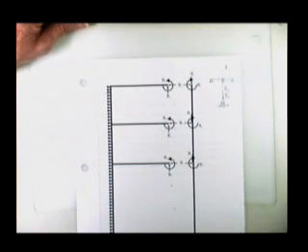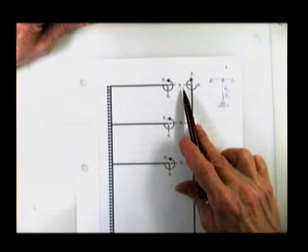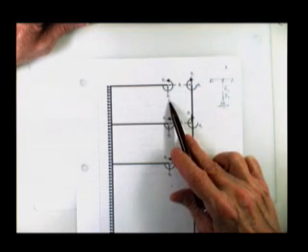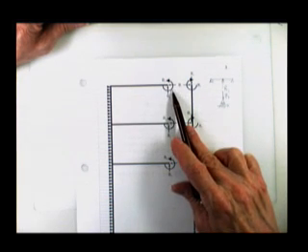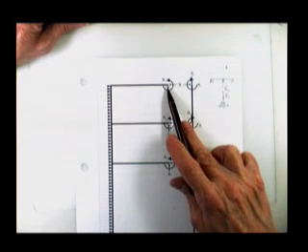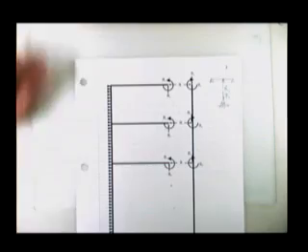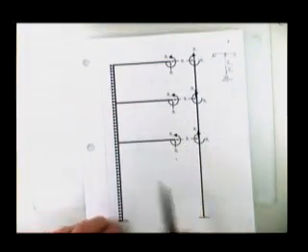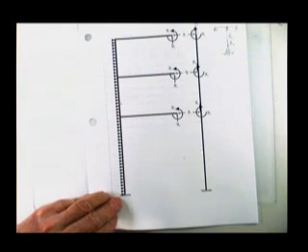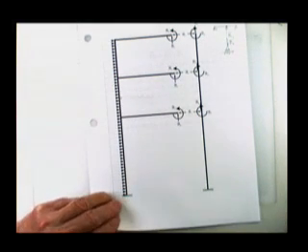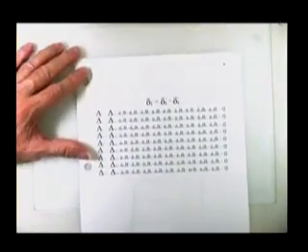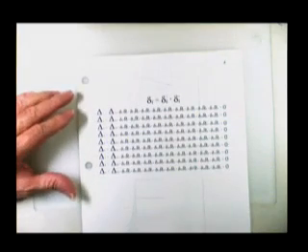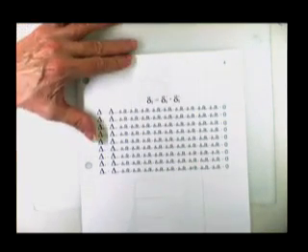So here will be our redundants. R1 will be the axial force in the top member. R2 will be the shear on the right-hand end of the top member. And R3 will be the moment on the right end of the top member. R4, 5, 6, R7, 8, 9. Here's your final set of equations. Well, yeah, nobody said that it would be short or easy, but that's why the dollars are big and nice.